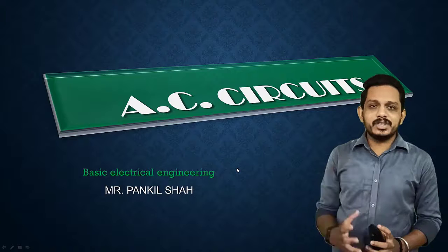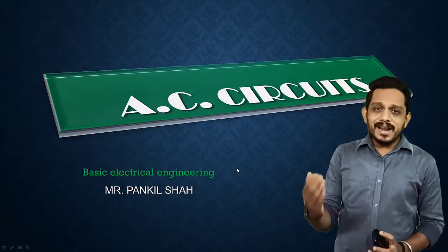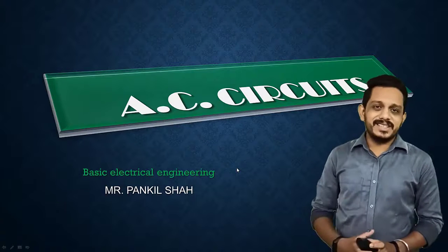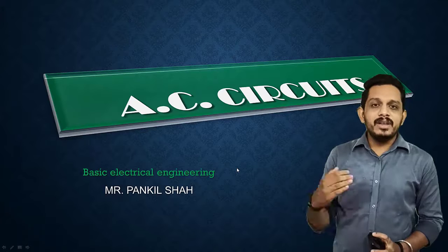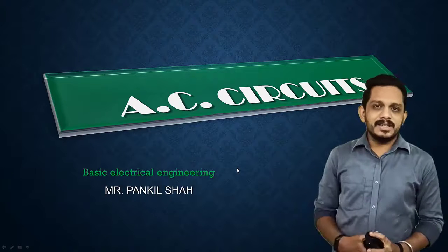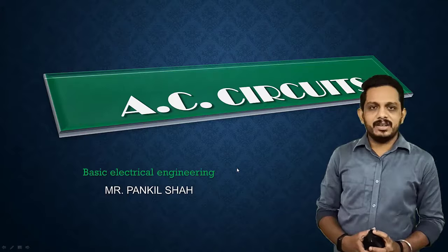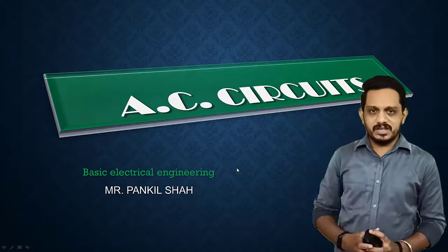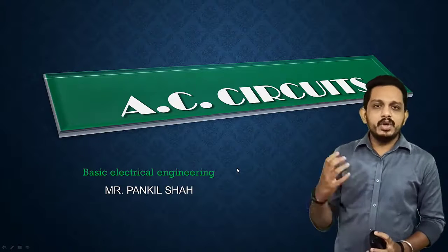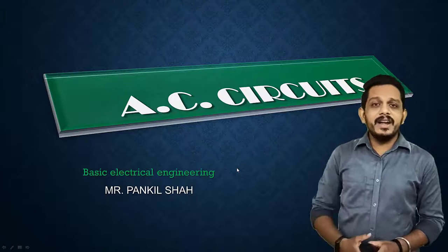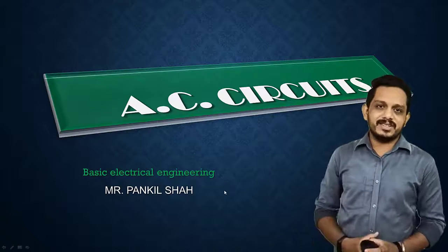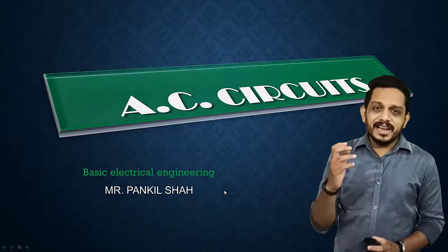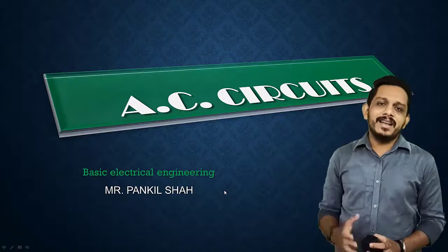So now in this video you will see some analysis of series circuits. You have to analyze AC circuits which have more than one component. We studied an inductor, that was a pure inductor, meaning the inductor did not have any resistance. But in this video you need to understand what happens if the inductor has some resistance. To represent that practical inductor, we represent the internal resistance in series with the inductor.